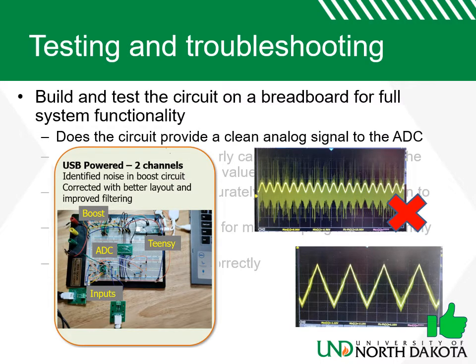Here are the testing and troubleshooting tasks that I did. First, I built and tested the circuit on a breadboard for the full system functionality to make sure readings were coming in properly, you're getting good digital data, analog signals are clean, everything's functioning properly. On the USB powered breadboard, I noticed there was a lot of noise in the boost circuit, and corrected it with a better layout and some improved filtering to get a nice signal that we could work with.